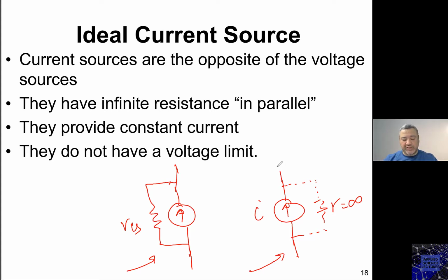We assume that our source, voltage source, current source, or power supply in general, is ideal, which means it has infinite power and can provide whatever power we want. Practically, this is not correct. You have to be careful and look at the maximum power you can get out of the power supply.